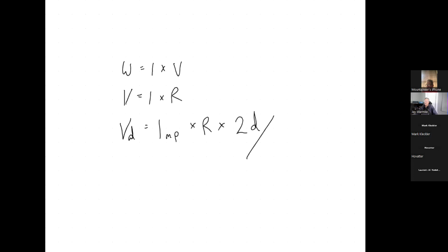divided by 1,000 feet. The reason we do twice the distance divided by 1,000 feet is the resistance characteristics. The resistance you're given is ohms per 1,000 feet. And you get that out of the NEC through the table. The table's in your book.